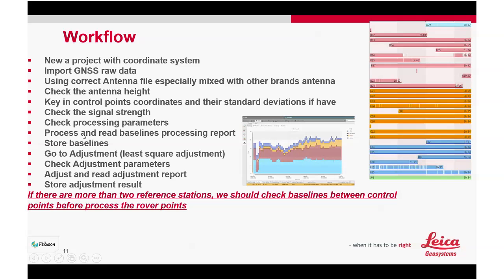After processing, we need to understand the baseline reports. Then after that, when we are happy already, we store the baseline. So next we can go to adjustment. Then we can check the adjustment parameters and then we adjust. Do the adjustment and read the adjustment report. And then we store the adjusted result.